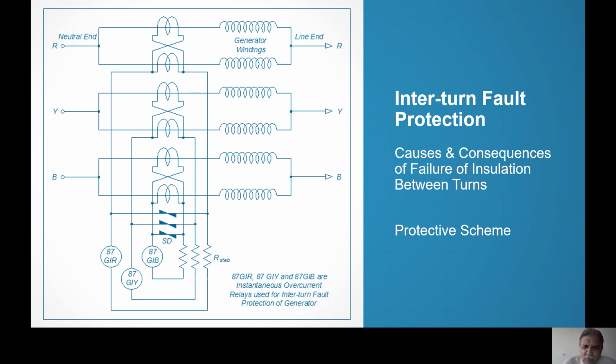So interturn fault protection is simple, but because it is going to result in a very severe fault, line to ground or double line, this is also instantaneous and class A protection. That is for your information. So it is simple protection, nothing difficult. All calculations, methods, knee point voltage requirements of the CTs, everything is the same. No doubt, we are going to talk about CTs in detail afterwards.